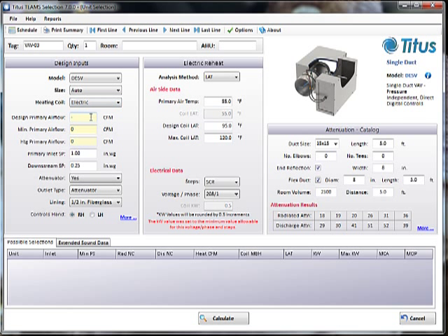Okay, so on this one, let's put some reheat on it. Let's do our same 1000 CFM, say. It auto-populates the minimum primary and heating. I think we'll leave that where it is. It's also changed our unit to attenuator yes, so that when you get the electric heat, you get it in an attenuator section.